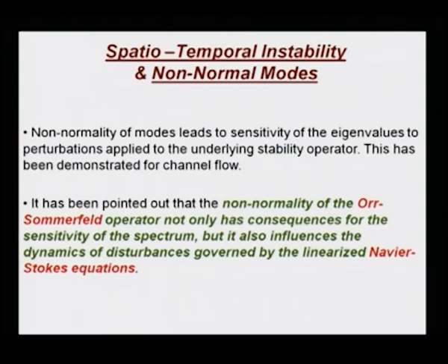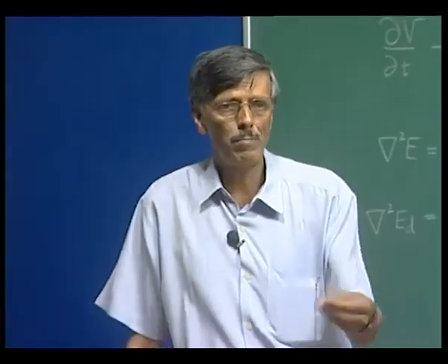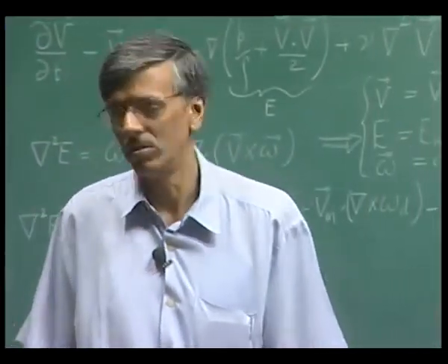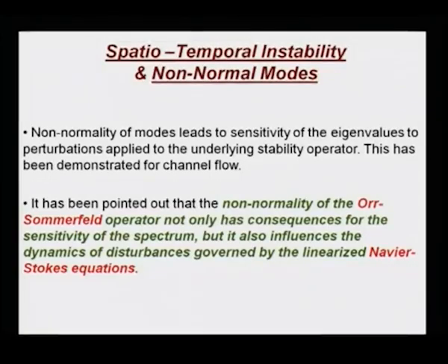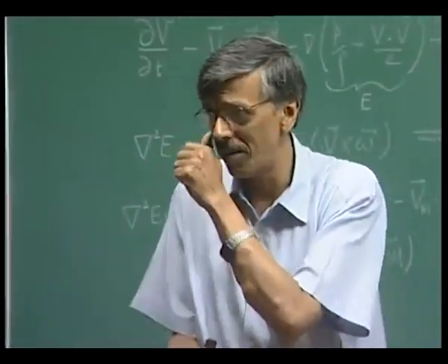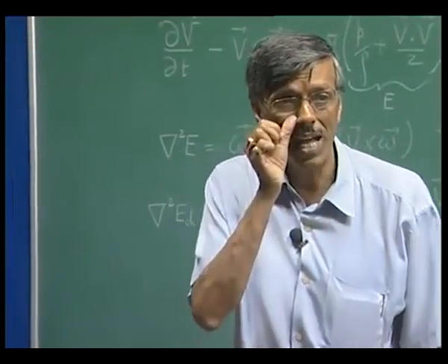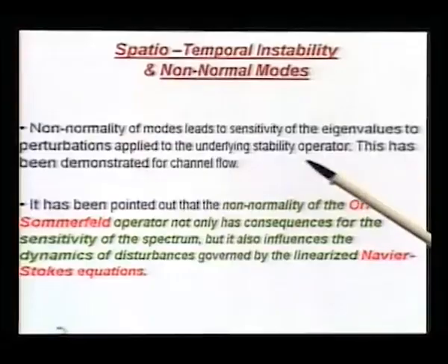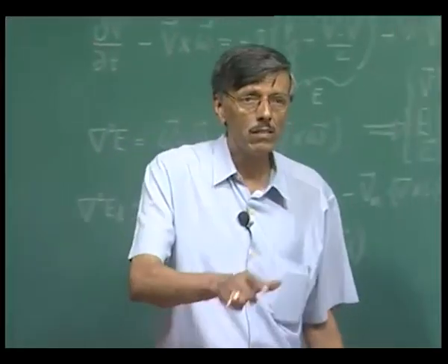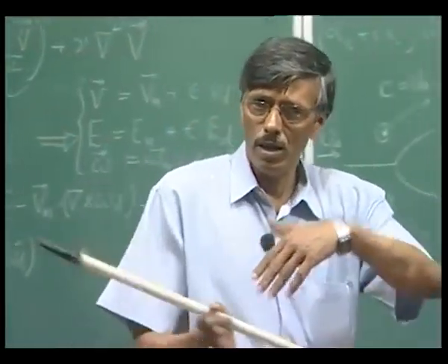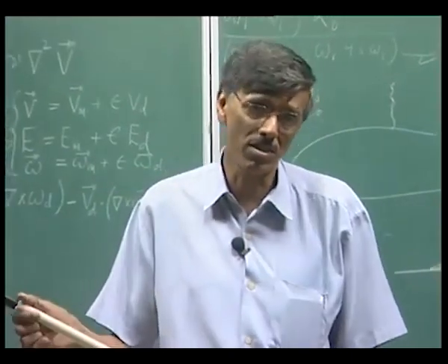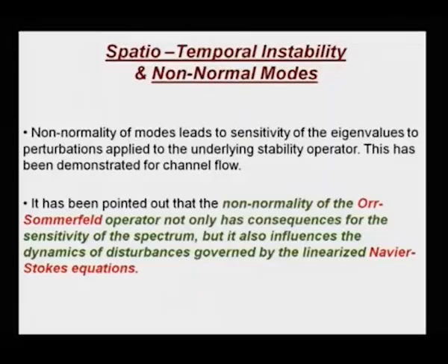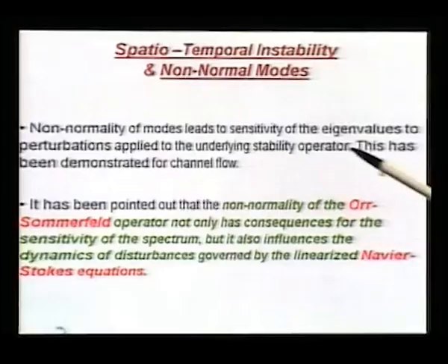Non-normality of modes of a fluid dynamical system makes them very hypersensitive to background disturbances. So if that is so, then theoretically you are getting some kind of eigenvalues, etc., but they are so susceptible to background disturbances that you can get some kind of spectacular growth in the presence of disturbance itself. And this has been demonstrated for channel flow.